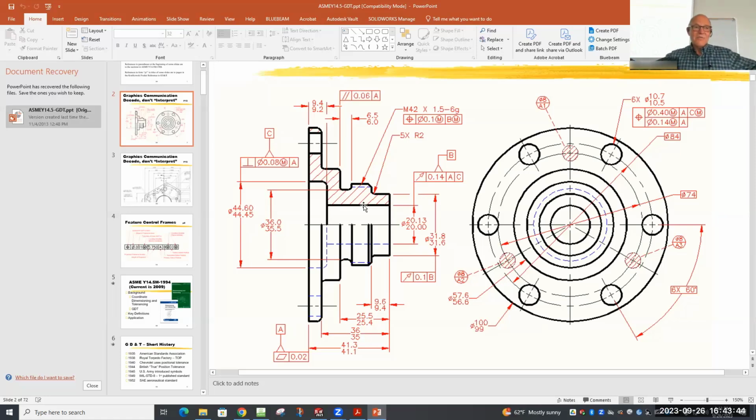If you have something long, like a drive shaft on a vehicle, the drive shaft on a pickup truck that goes from the engine back to the rear axle, that's really long. You put that someplace and start spinning it. The total runout really matters on that because when you're driving along, in one of the shops I worked in, we used to actually straighten drive shafts with a hydraulic press, so that they wouldn't have that kind of runout. That's always interesting too, because you have to over-bend it in order to straighten it. If something's like this, you have to bend it past the straight point so that when it comes back, it comes out straight. And you're using a hydraulic press where if something comes out of it, it comes out like a bullet. It's just really a mess.